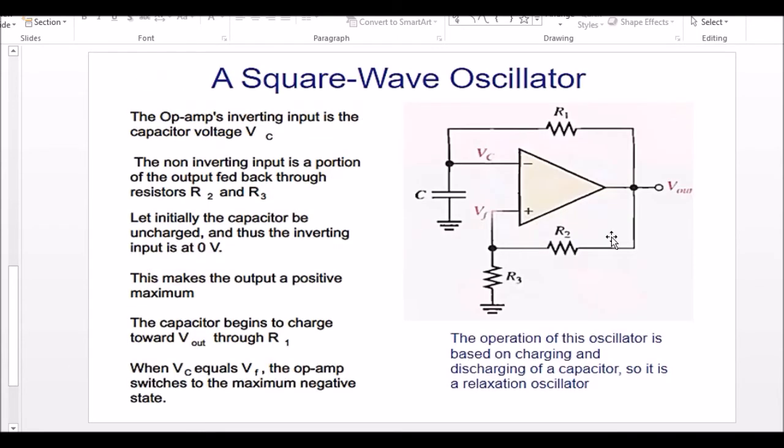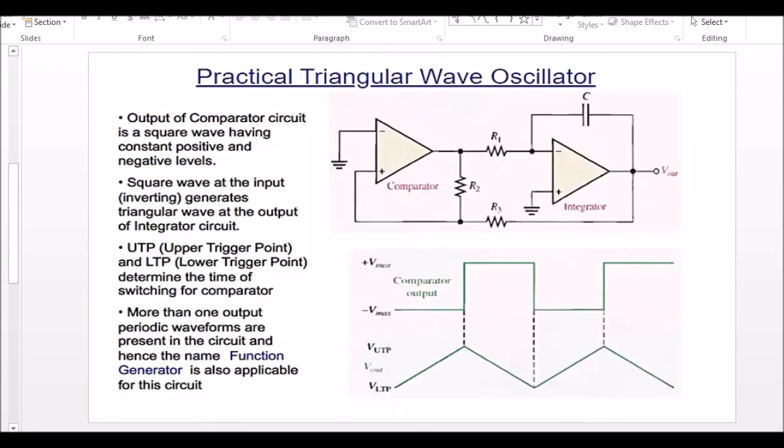So when you are actually using this circuit, now your non-inverting circuit has a set of 2 resistors in the feedback loop. These are feeding back the output voltage in the form of a voltage divider, and it's somewhat similar to what we did in your initial comparator circuit. If you remember what we did in the comparator, we took the output voltage and fed it back to the positive loop with the help of a voltage divider. And what does a comparator do?